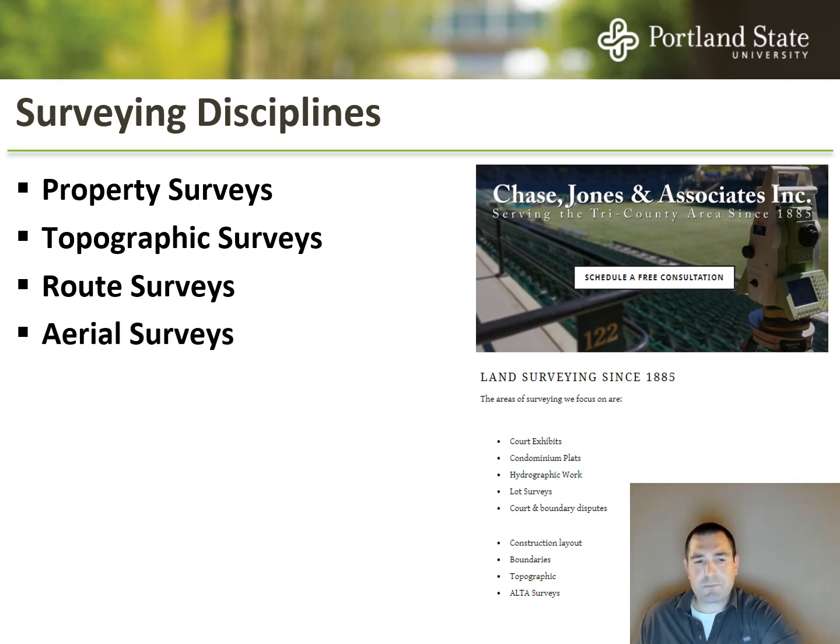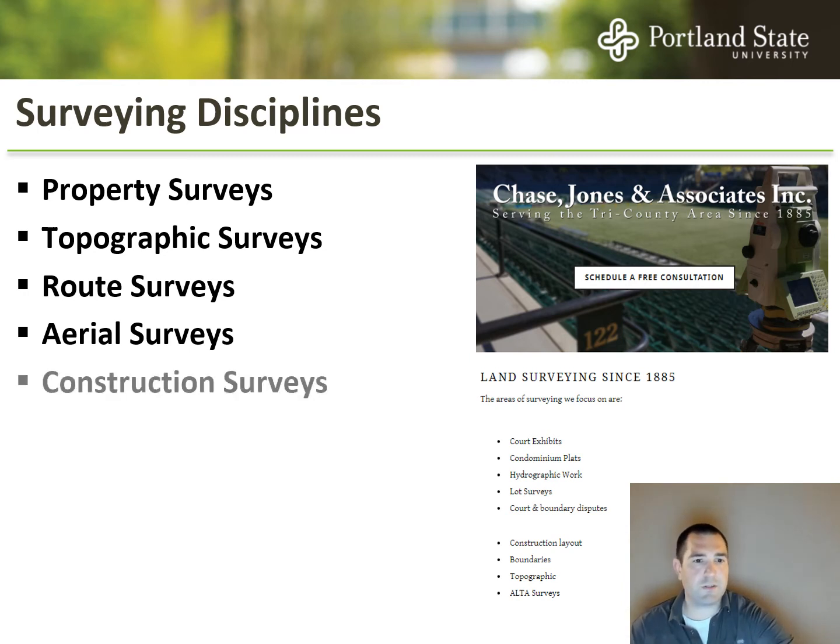Aerial surveys. Now this could be pretty broad. This could involve things like LiDAR nowadays. We'll talk about that towards the end of the term in a lot more detail. It might involve having a flight where we have a laser do distance ranging. We might have photogrammetry, where we take photos from a bunch of different angles and we use a lot of processing algorithms with a nice fast computer to make a 3D model just based off imagery alone. There's a bunch of different ways that aerial surveys can be implemented nowadays, especially with new technology.